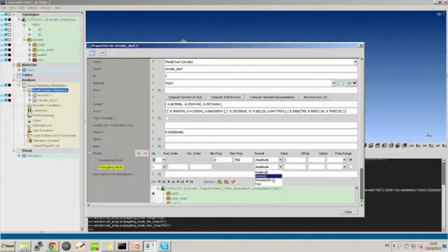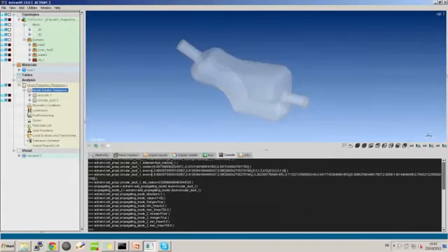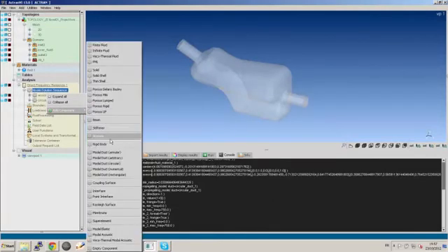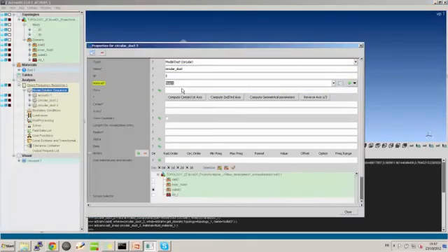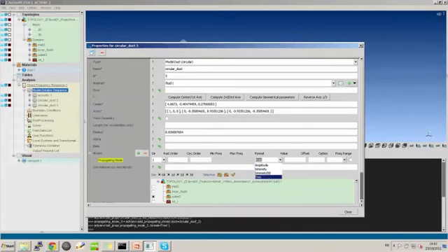The other mode will be a free mode for ensuring a non-reflective boundary condition at the inlet. I am also specifying the range at the same time. You see that any type of operation that I am performing here is translated into the session file. I can now also create this for the outlet. Here I am pointing towards the outlet. I am assigning the same material, computing the geometrical parameters that are slightly different in this case. And now I will also specify a non-reflective boundary condition at the outlet in order to allow an infinite duct.